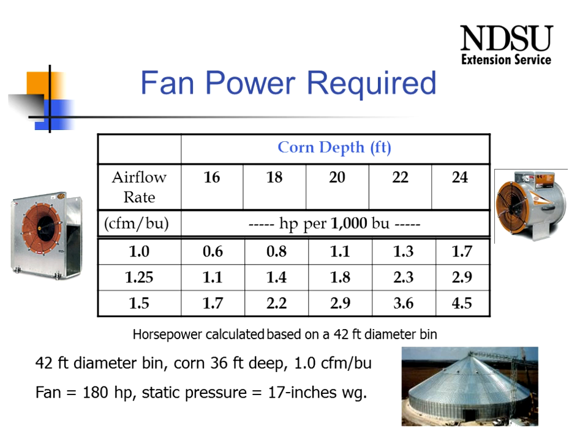I mentioned that the depth of the corn has a big influence on the airflow and the energy efficiency of that system. What we have heard over the years is a rule of thumb of 1 horsepower per 1,000 bushels. And that works fine as long as we're looking at an airflow rate of about 1 CFM, or cubic foot per minute, per bushel.